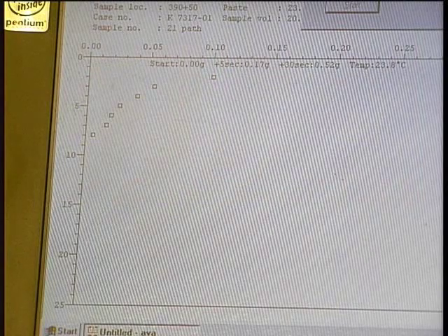The computer captures this weight every minute and a graph is plotted in real time showing the weight change. After 10 minutes, the bubbles become very small and the weight changes are likewise small. The test continues until there is no weight change recorded for 2 consecutive readings or a maximum time of 25 minutes. By this time, the bubbles are almost imperceptible. These tiny bubbles are the ones that are most efficient at producing a good spacing factor.